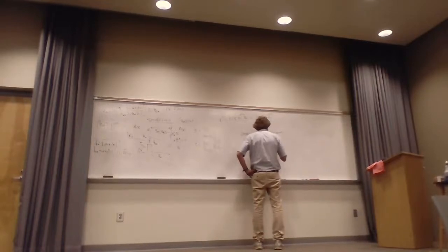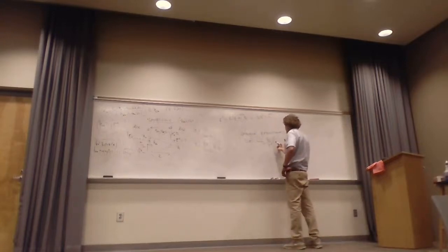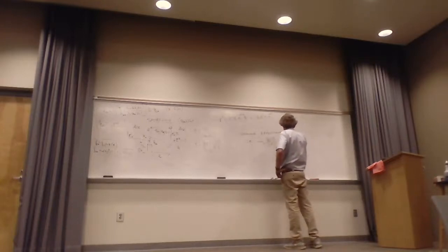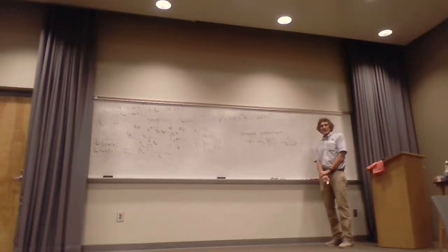And you better put magnitude here, because some of you may end up having a phase in there. You'll notice how E incident occurs in both, so the E naughts will cancel. It's really 20 times the log base 10 of 1 over 2 tau 1 times e to the minus alpha L. And that is the shielding effectiveness of any reasonable shield.